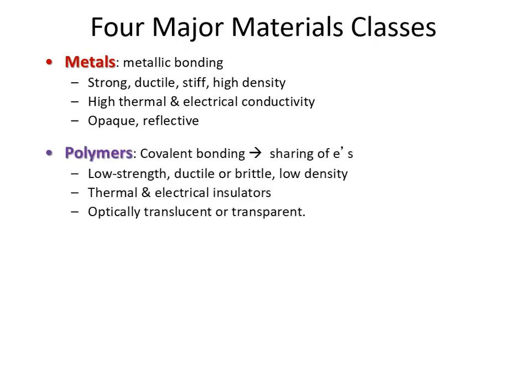Going to the other end of the spectrum, polymers. These are typically organic, although a silicon-oxygen structure is fairly common in the case of silicone polymers. These have covalent bonds, so electrons are very localized and associated with a given nucleus. They have a particular structure to the bonds. Again, for you chemists who remember your sp3d type hybridized orbitals, these form the basis of polymer structures, which we'll be learning about later on in the course.